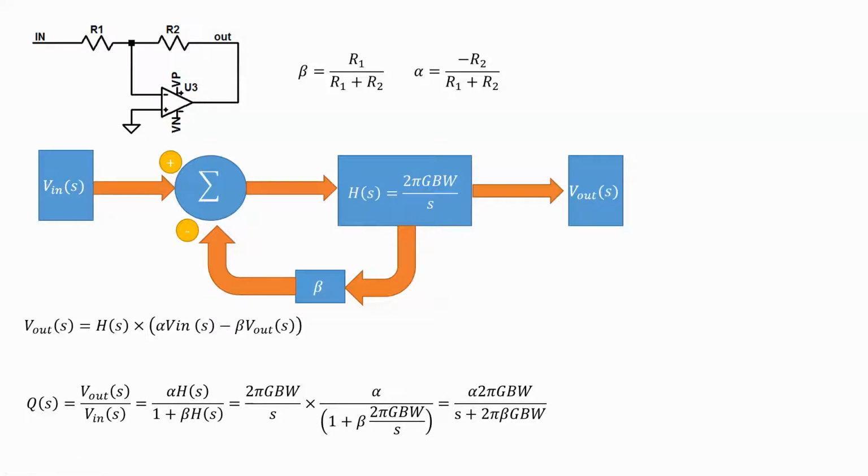Well, actually we just use superposition. We find what is the contribution at this point due to Vout? Well, you just short Vin and you get R1 divided by the sum of these. And then how do we do the input? Well, you just short Vout, which is the voltage division.